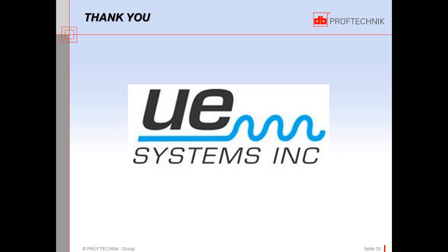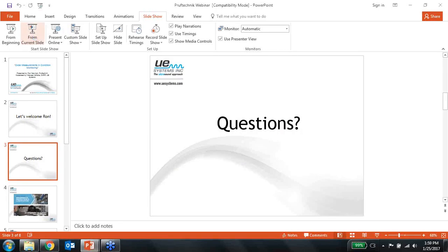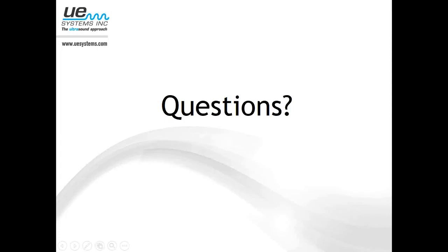one accelerometer correctly placed on the bearing, and I'm assuming that this gentleman or lady is in the paper industry. He's probably referring to felt rolls or dryer can rotational speeds, possibly. But yes, the answer would be one accelerometer, typically in the axis of least stiffness. For most machines, that would be horizontal, but it might be axial in the case of some of those issues peculiar to her industry.